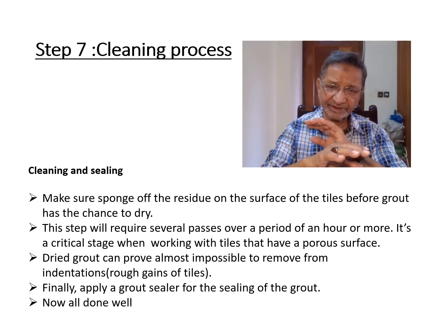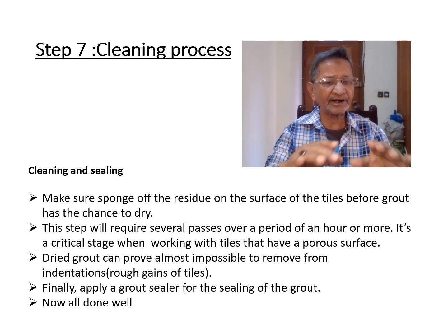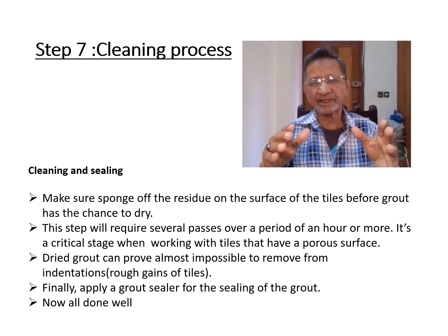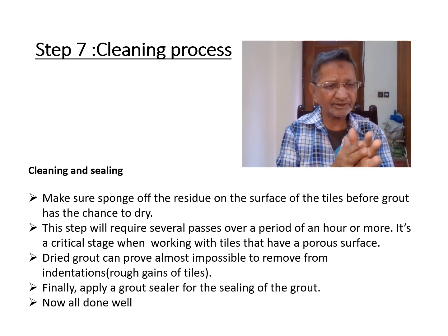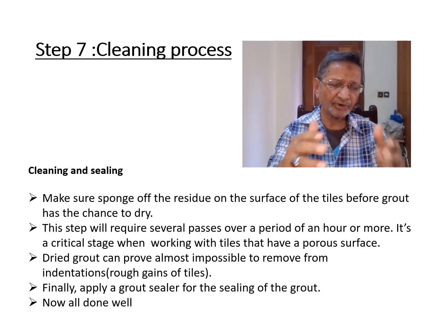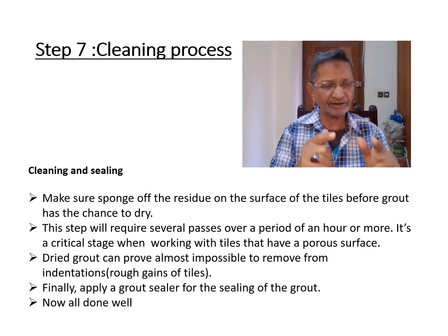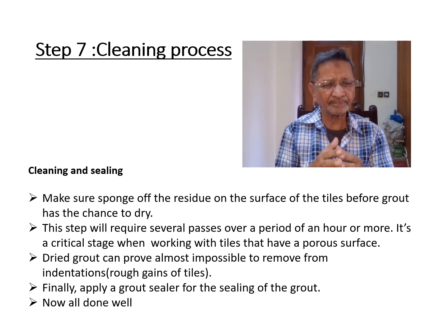If it dries up, it's very difficult and mostly impossible to remove the dried grout. So you have to remove it immediately, before it dries, while it is still wet. But make sure that the joints are filled properly.